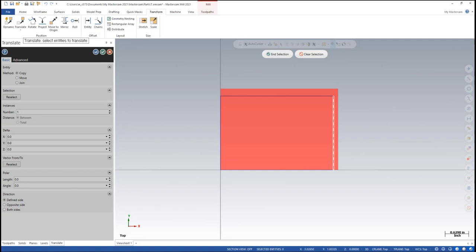And then it'll ask you to make a selection. You can pick a single entity if you want, and it'll highlight, and if you pick it again, it'll deselect it. Because we're working with wireframe, if you hold shift and then pick a piece of wireframe, it will chain everything that it can. So if we hold shift and click it, it now selects all of our wireframe.